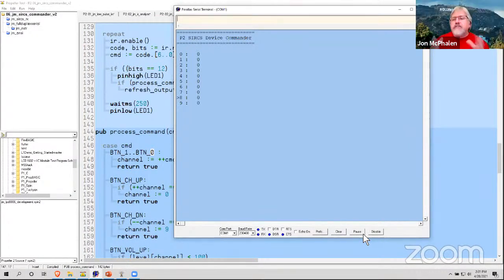Yes. Just for terms, I refer to the entire transmission as a frame, and then there are packets within the frame. So in my definitions, every time I press a button, I get a frame. With this remote, I found that each frame is 3 packets. With this other remote, I find that each frame is 5 packets. The interesting thing is Sony never officially published the SIRCS protocol. This has been derived by people like us.